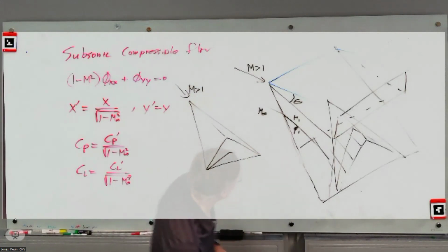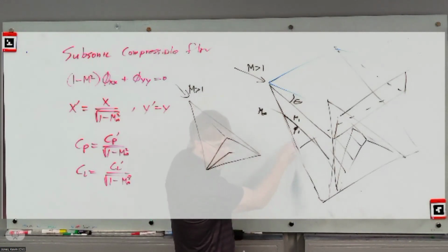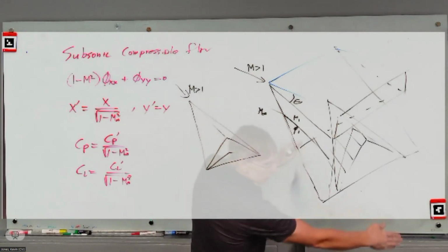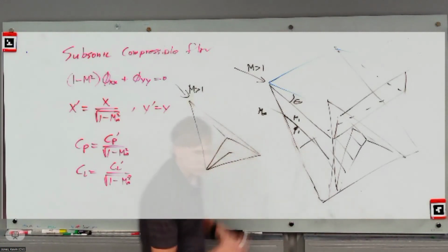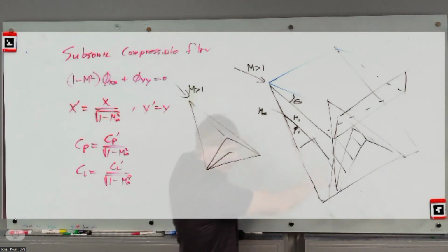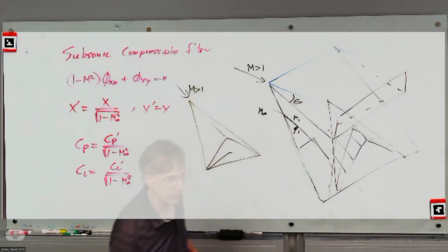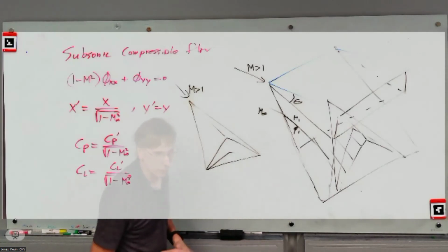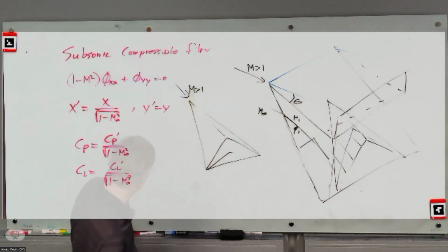With this, in the old days, you could literally have an isentropic code here. You could apply a shock jump relation here. You could have an isentropic code back here, and the shock would be perfect. And any noise that would normally be created by trying to shock fit, seen in CFX, all that would be gone. So that's the closest you can get to perfect. But again, it only works for cases where you physically know where the shock is.